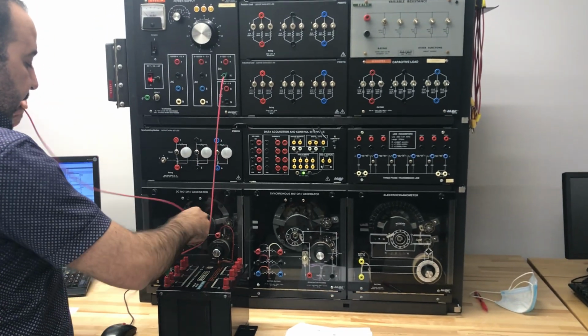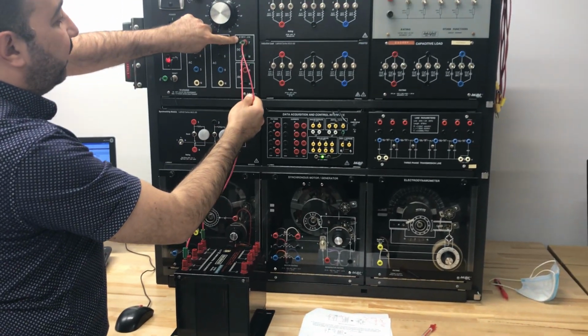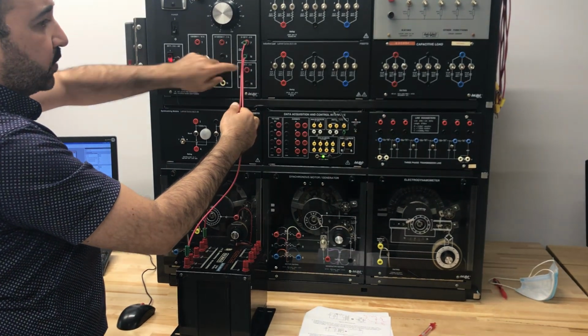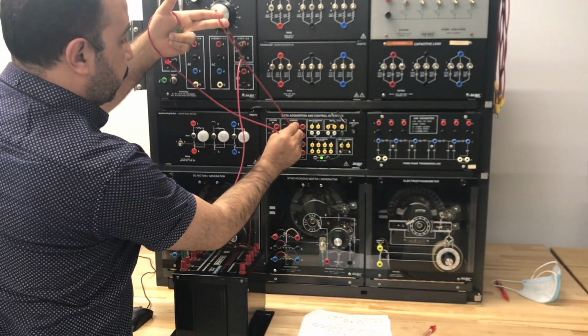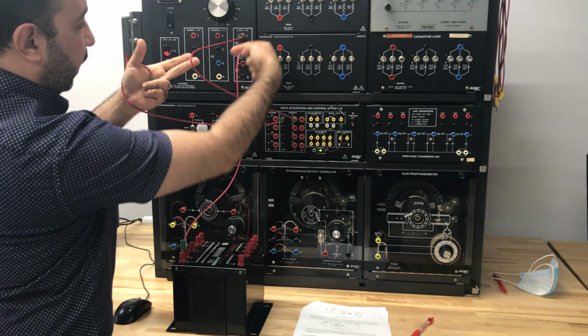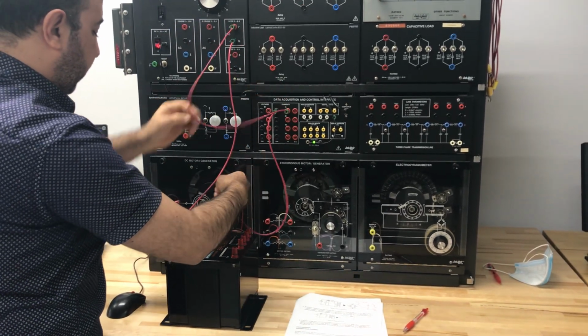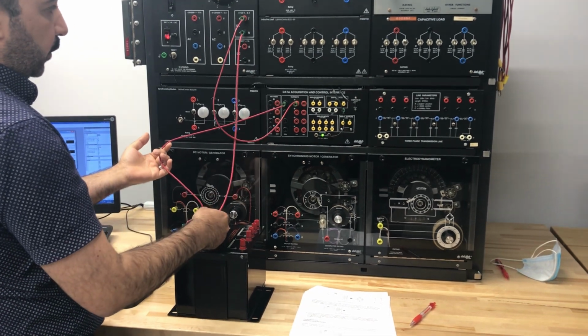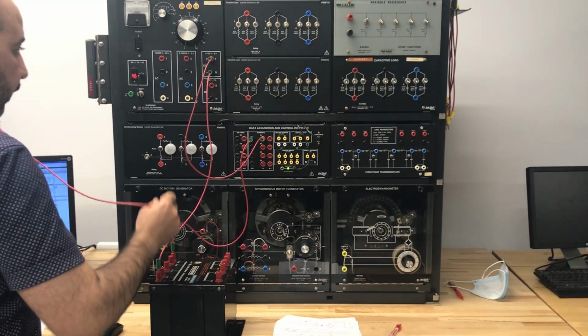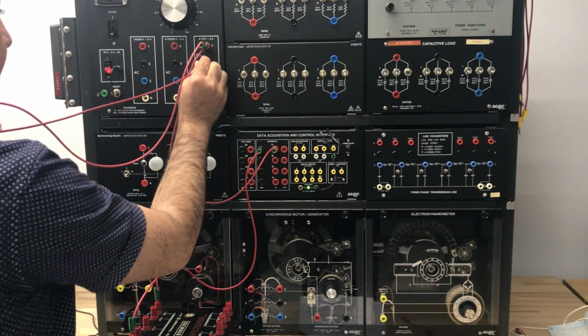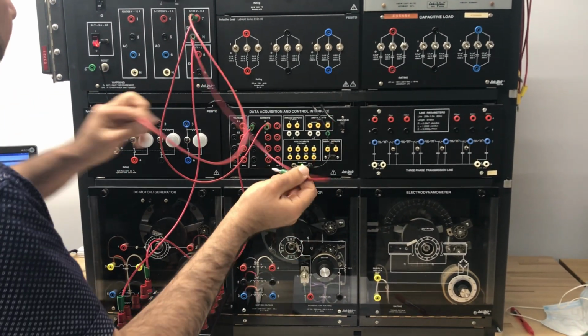So what am I going to do? I'm going to connect this guy to DC source and this guy. But pay your attention, we are going to use variable DC, not fixed one, because I would like to use very, very small supply voltage. At the same time, I would like to measure the current and the voltage, so I will connect this guy to this guy, which is the ammeter, so the current is going from this guy to the ammeter, going back to my supply, my transformer. Then I would like to measure the voltage as well, so I will connect this guy and this guy to E1 to measure the voltage.